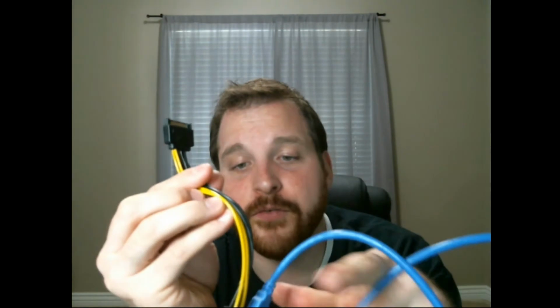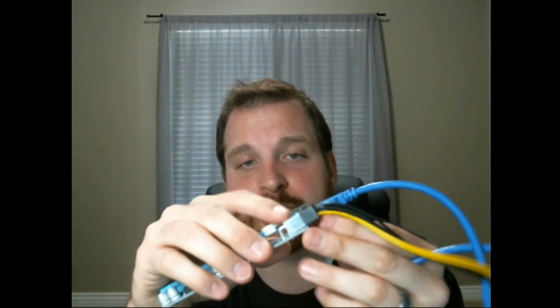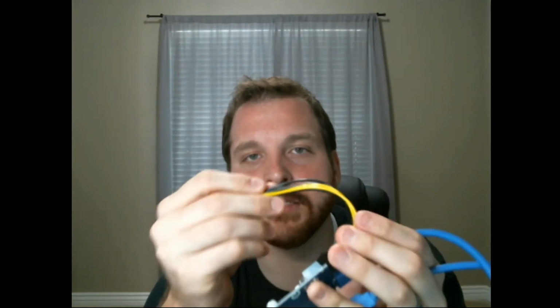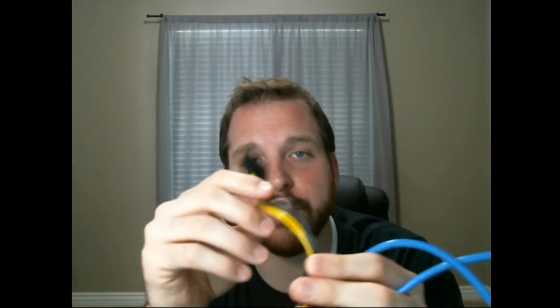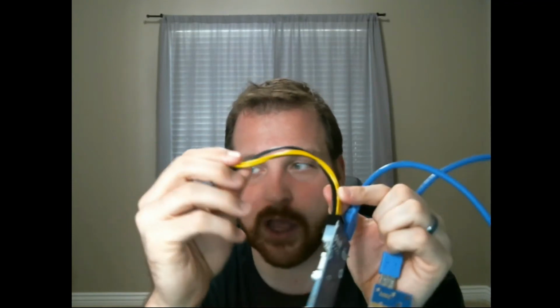Now this piece here is power for the riser itself to help the riser function. And so if your riser comes with a power port, 9 times out of 10 you have to use it. On some motherboards, they're a powered motherboard for the risers. I've found in my experience that doesn't work, that it's just safer to run the power cable. I would always recommend a SATA cable, not the Molex style. That's the 4-pin.